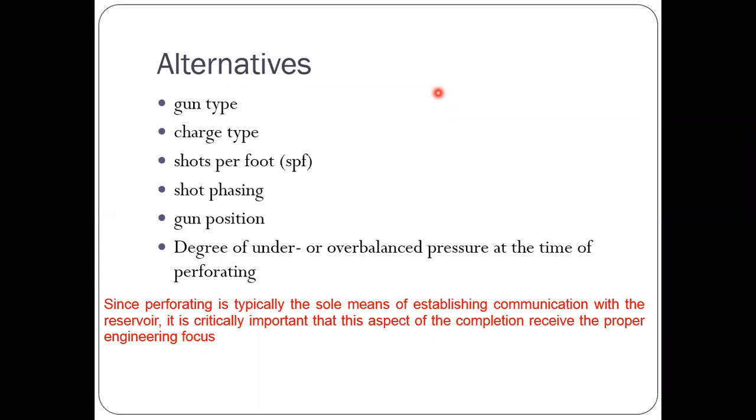So since perforating is typically the sole means of establishing communication with the reservoir, it is critically important that this aspect of the completion receive proper engineering focus, because this is the only way that you communicate with the formation. So this is a communication channel between the well and the formation.